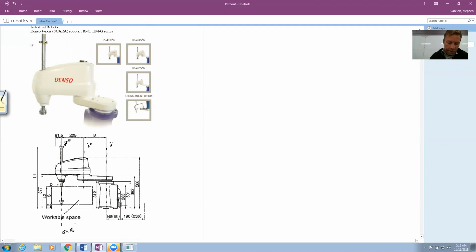Next we assign the Z-axis. We'll put Z0 along joint 1. I'll put Z1 along joint 2. Z2 is going to go along joint 3, the Prismatic. I think of the Prismatic in the normal direction going down, so I'm going to run Z2 down. Z3 is also going to come down. I'll line up Z3 with Z2, and then finally Z4 is my last frame. I'll put it out at the workspace of the robot.